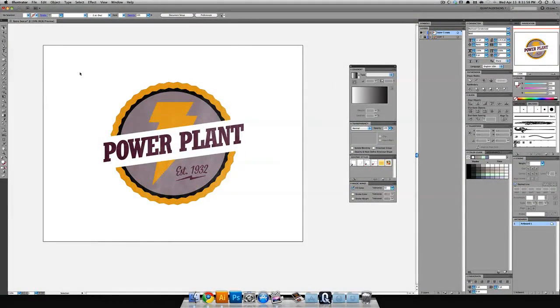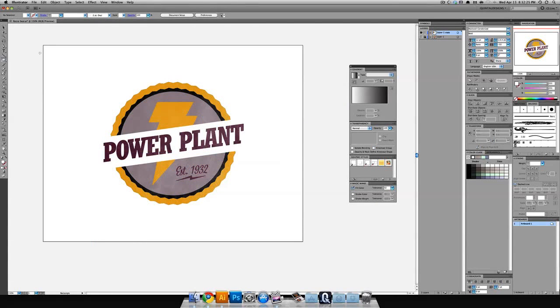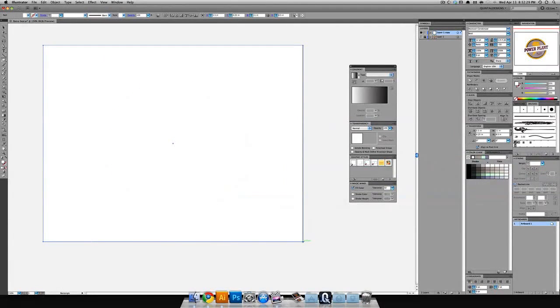Now let's hit Command, Option, and 2. And that'll loosen up or make our bottom layer selectable. Select everything, Command A, then Command G to group it. Now this is all together, and you can see the transparency again reads normal because of this group, so now we have another method to select this transparency. We're going to go ahead and grab the rectangle tool now to finish this up and just give it a little bit of a background.